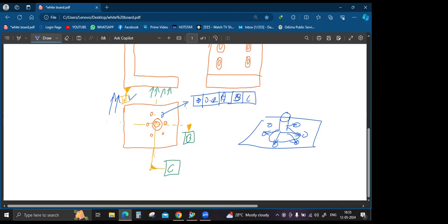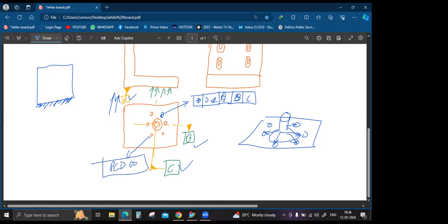Okay. So whenever we are going to start a machining process, suppose we are having a block, sir, initially we have to face this one and we have to set that one first. Cool. So which surface we are machining first, that will be our reference A always. Okay. Then according to B and C, we have to control the position of these 6 holes. So we have to provide the PCD value. I think we have given it as 60.